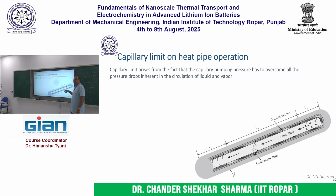Here the wick will become devoid of the liquid coolant and the wick will dry up, and this is called the dry out failure of the heat pipe. Then latent heat absorption will not be available to you, and only conduction through the heat pipe body will be available, and that will lead to a rise in the temperature of the device that you are trying to cool.